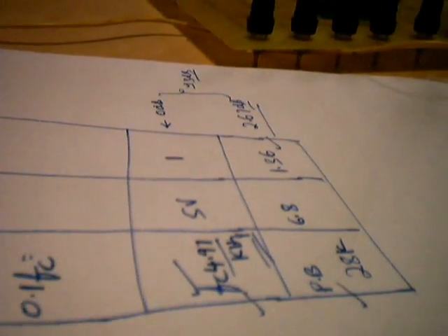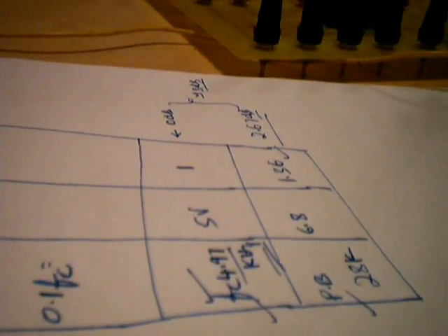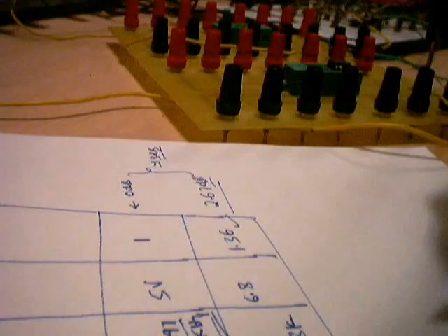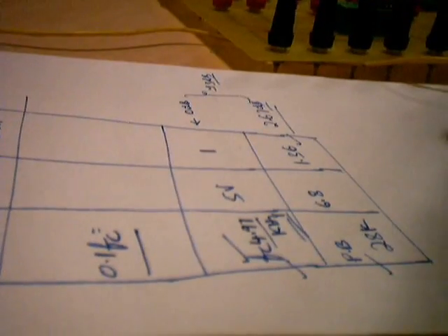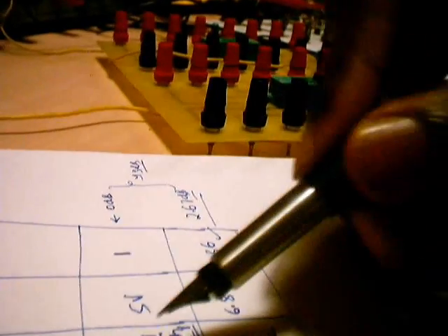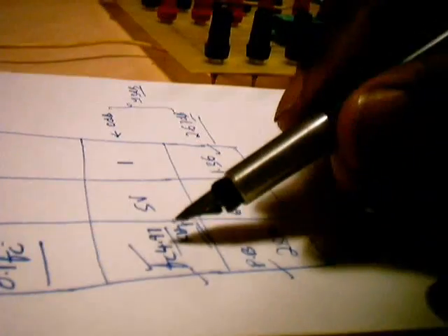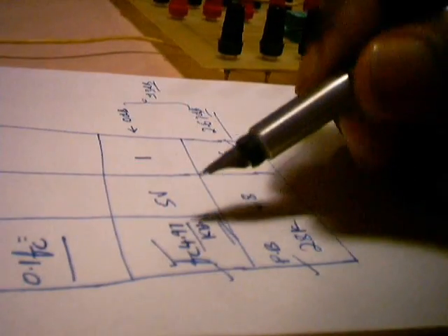Now let us find the roll off. To find the roll off, we need to keep the frequency of the input signal in the stop band. The stop band of this high pass filter is less than the FC. So that's why we take 10 times less than the FC. In your low pass filter, we made it 10 times more than the FC. Now it is 10 times less than the FC, which happens to be 0.497 kilohertz, exactly 497 hertz. So we reduce the frequency from 4.97 kilohertz to 497 hertz.